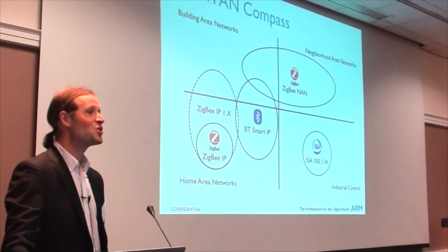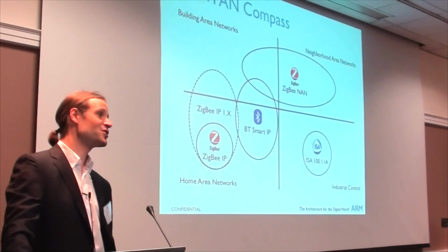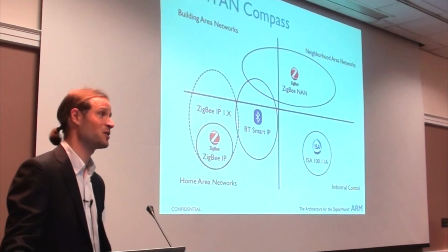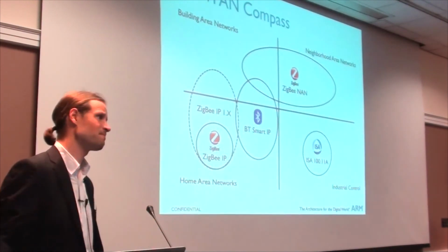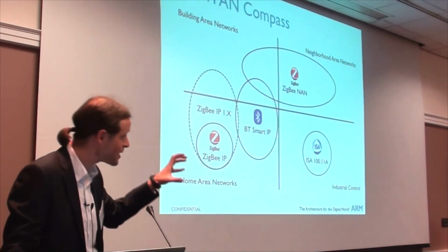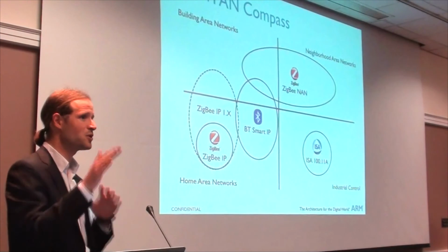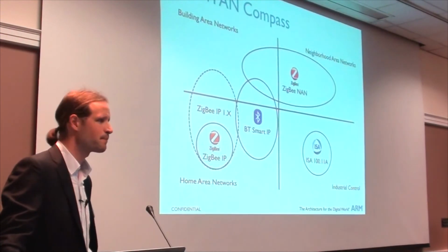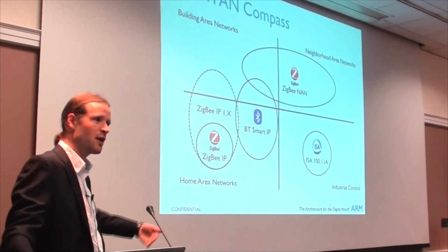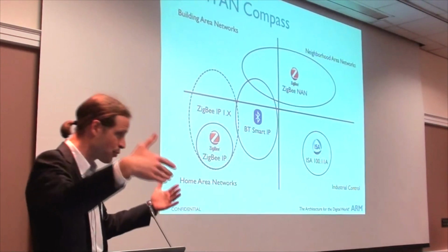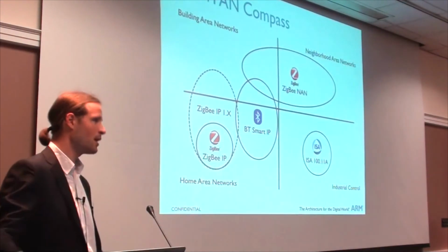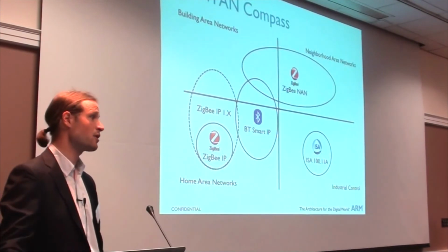Well, the G standard is lots of things. So everybody supports a subset of the G standard. But that's normal. Nobody supports all of the G standard because you can configure it for everything. That's why you need a profile also like Zigbee NAN, where you actually specify what settings you use from the G standard. Otherwise, you'll never get full interoperability. Yeah, the 212 is a great chip. And as you see standards like this that push the radio technology, you'll see all the chip vendors able to support those settings too. So as we have something like Zigbee NAN, it'll pull the market, and you get everybody started. So you'll see a lot more silicon for sub-gig in the future.